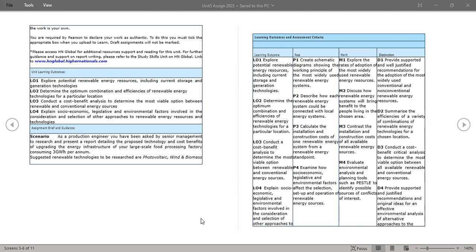So for example, if you start off with 20% efficiency, it could well drop below 18% after 20 years. Now, that doesn't sound like much of a drop, but initially it is only 20%. So 20% to start with, a 2% drop is really a 10% drop over that 20-year lifespan.